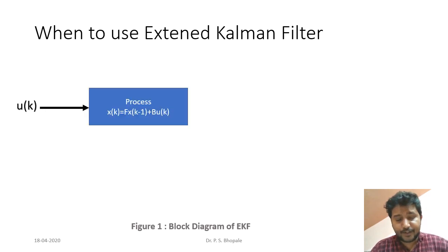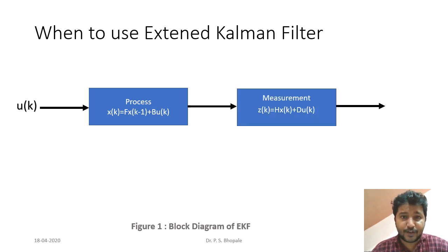So in this linear Kalman filter, we see a process model and a measurement model where the current state is passed through process matrix A or F, and to obtain the next state, a control input U is applied through control input matrix B. Then to obtain the measurements, we apply a measurement matrix H or C in other cases, and control input U is again applied, and we get an output Zk.